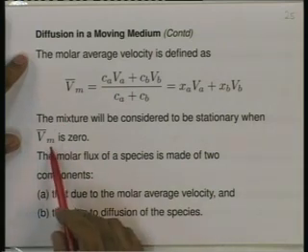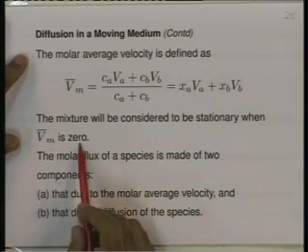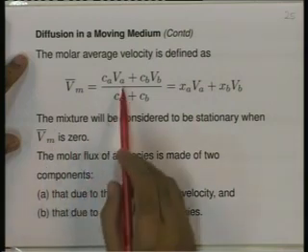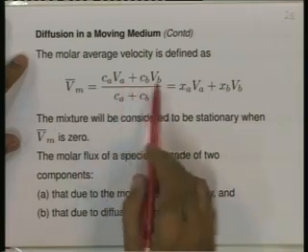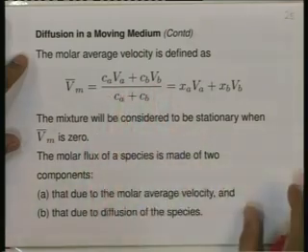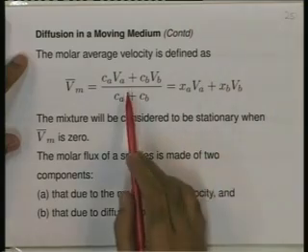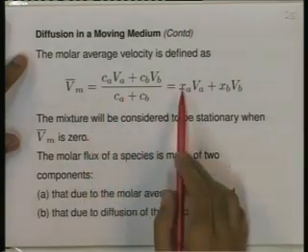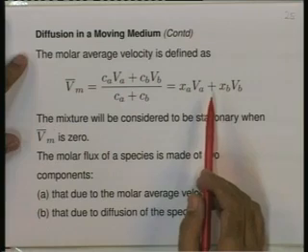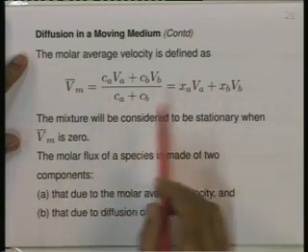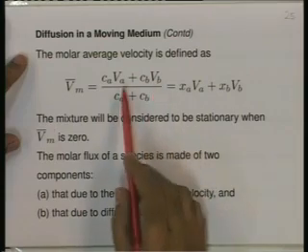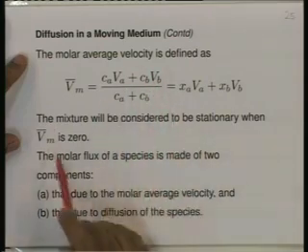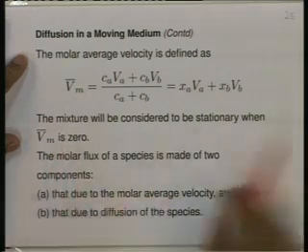Notice that the molar average velocity may be 0 when Va and Vb are non-zero but have different signs. So, if the bulk movement of A is say from the left to right, and bulk movement of B is from right to left, it is possible that the magnitudes of Va and Vb are such that they cancel out with this averaging and V bar m could be 0.